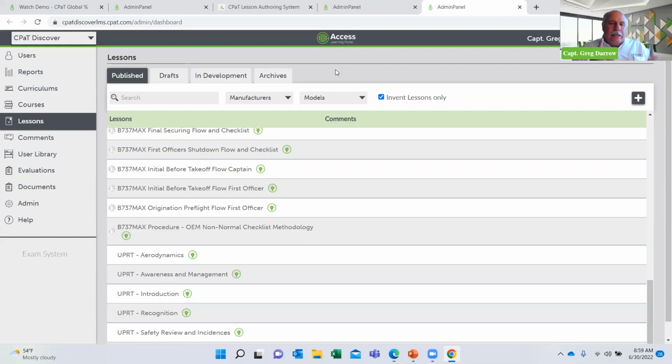And in that folder, let's say simulator day 1, introduction to the aircraft, would be the instructor's presentation, so the student can know what's being talked about, and 4 or 5 videos of the main tasks that'll be taught in that simulator session. For example, simulator day 4 is a lot of times single engine day. So in there, I'll have the instructor briefing. I'll have aborted takeoff procedures, and I'll have a video of that. I'll have a V1 cut video of that. Single engine ILS, single engine go around, single engine landing, let's say.